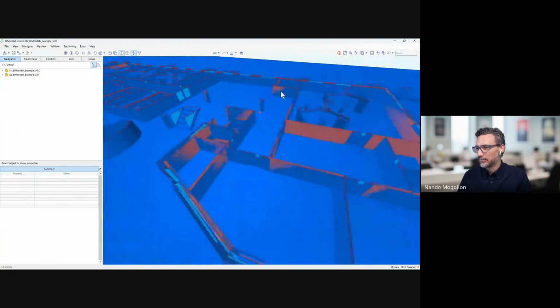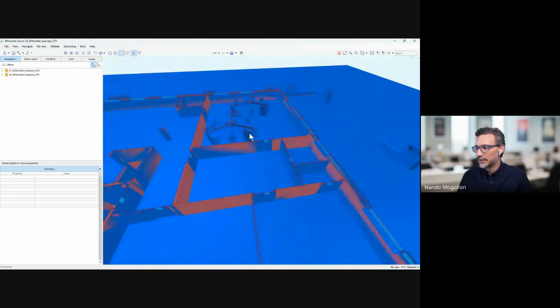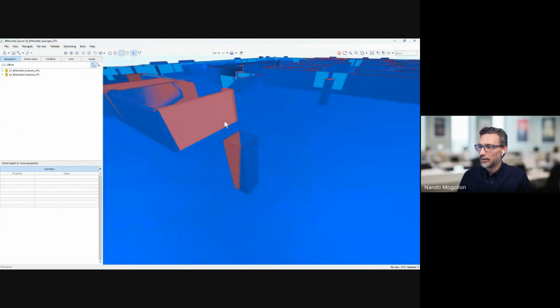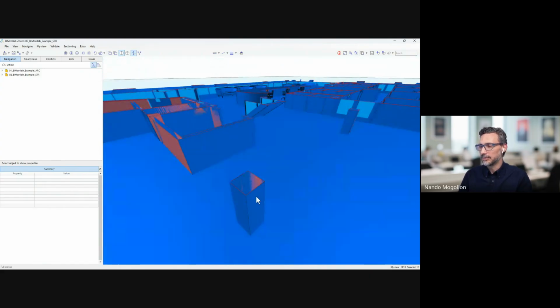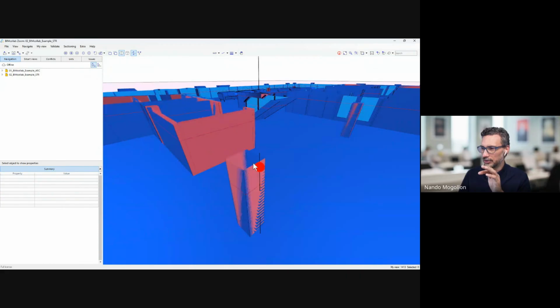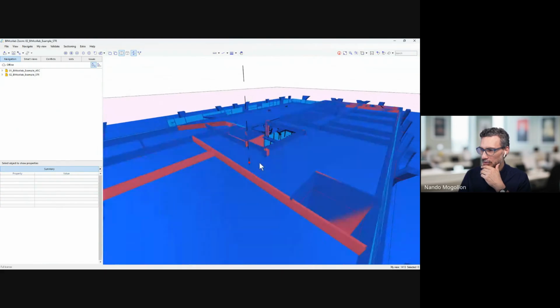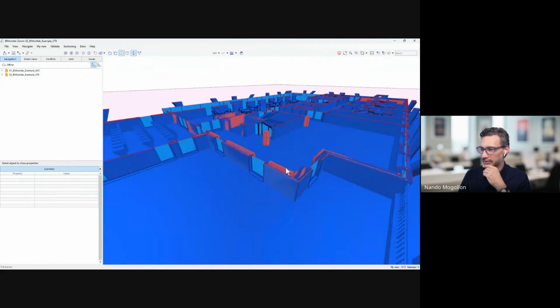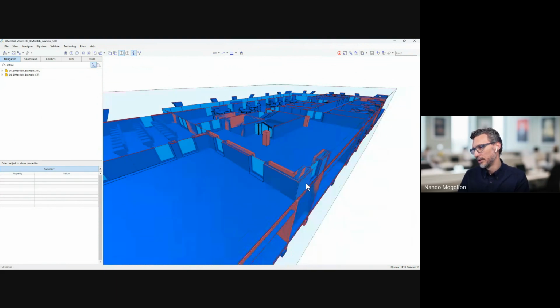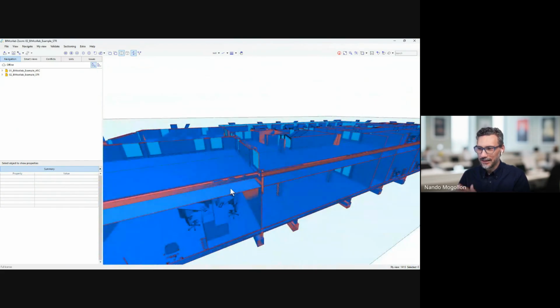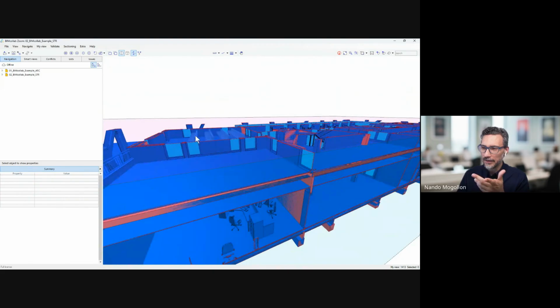I don't know if I had a mismatch in here, but this is the way I'll do that. Go and say, all right, those columns, they are in the same place. When you see that changing colors, they're usually on spot. And you can go like that and double check things, add another section and compare the slabs and so on. That's a simple visual check. I typically combine this, and it's suggested you combine that, with some level of transparency.